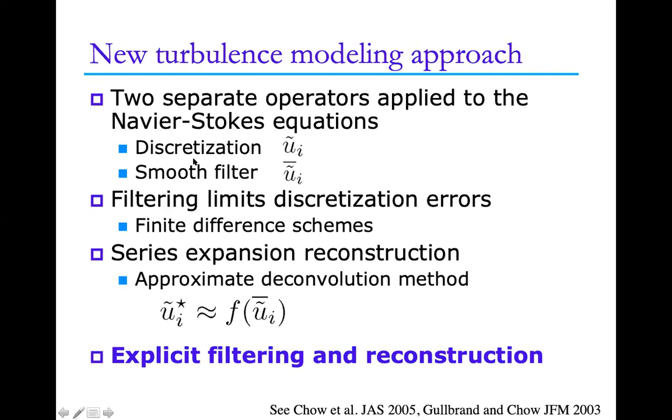In large eddy simulation, you apply a smooth filter to separate large scales from smaller scales, but we also have a discretization operator. And so if you separately consider a filter that's applied to the Navier-Stokes equations to generate the LES equations and keep that separate from the grid resolution, then there are some scales that can exist between the filter scale and the grid scale.